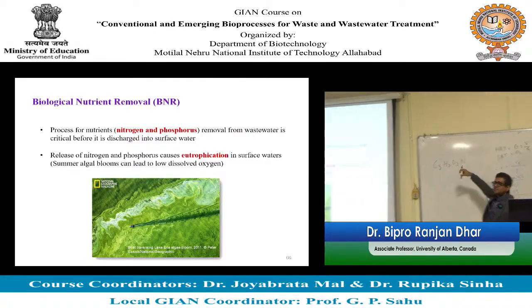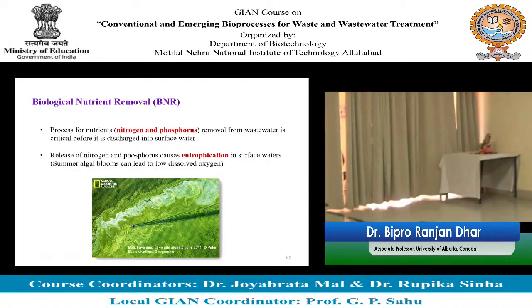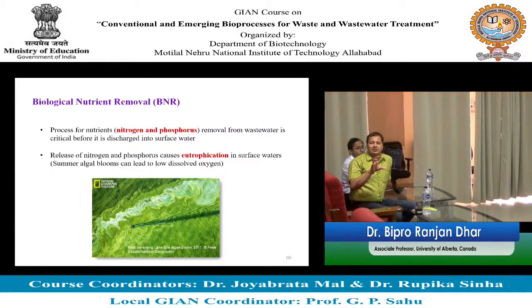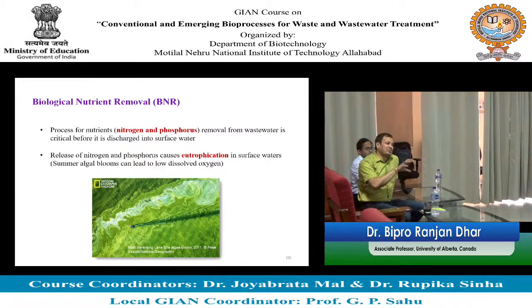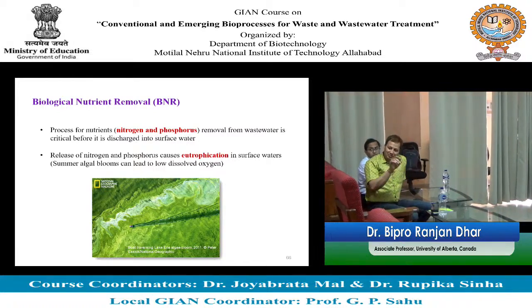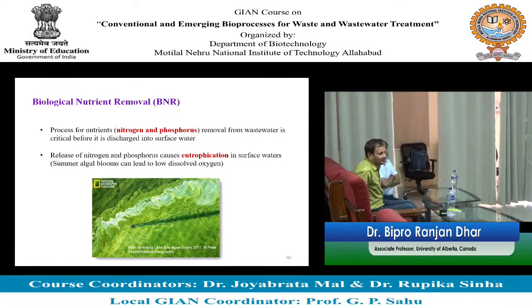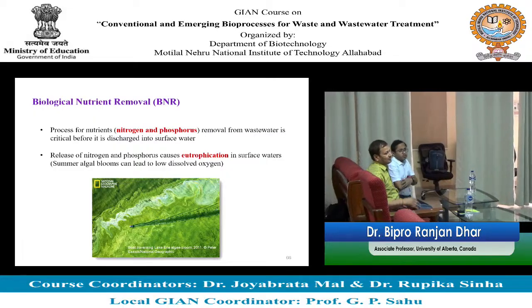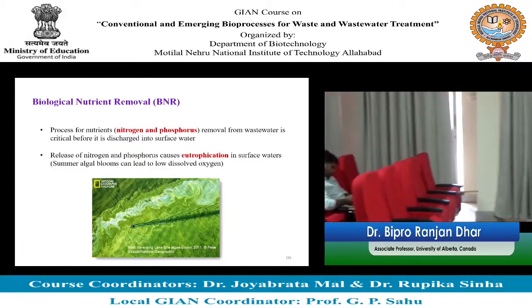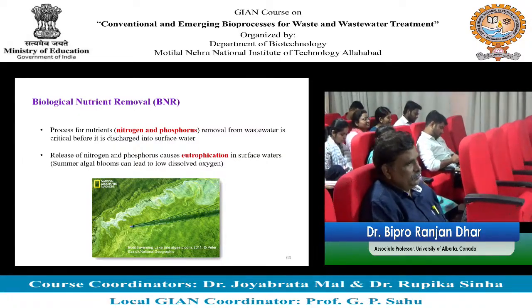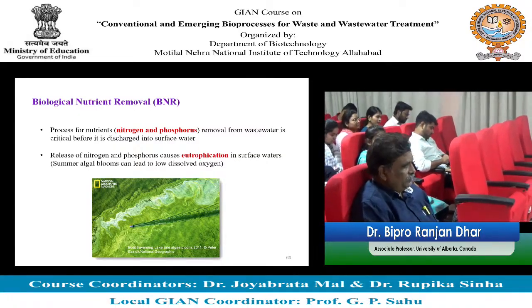Sometimes, suppose there is nitrogen deficiency, they add urea. And even sometimes if they feel that in the influent they have low BOD, then they add glucose also. But in typical domestic wastewater, you have an ammonia concentration of around 50 milligram per liter, which is enough. In industry mostly they do this kind of addition. Yeah, if you are talking about industrial wastewater, yes, sometimes it could be.